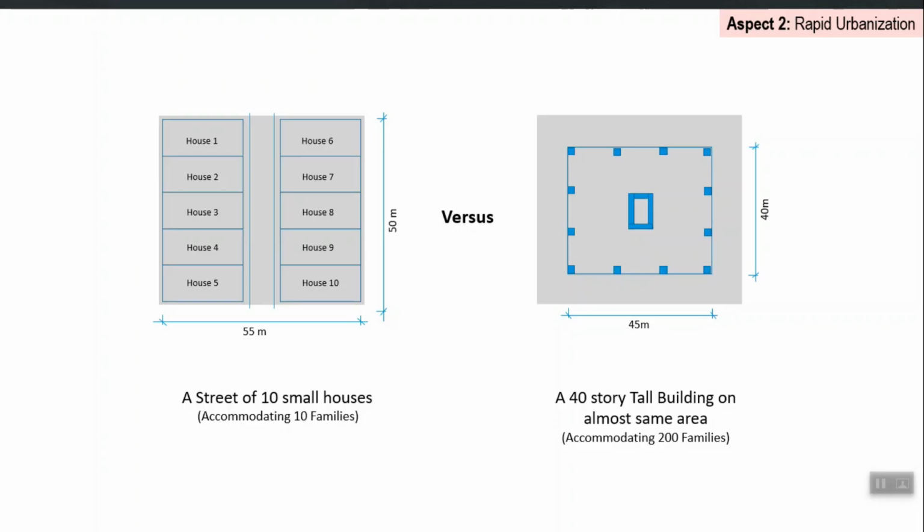Conventional structural design is based on building codes, right. So all structural engineers comply with the particular building code which has the jurisdiction at a particular location, at that particular site. So performance based design is an alternate approach, right. One approach is that you follow the letter of the code and produce the design repeatedly for each building. The design in that case will be the result of a cookbook type, prescriptive procedure. For each building you follow the same approach, come up with the amount of steel and cross sectional size for concrete, for example. But performance based design will allow you to try different things.